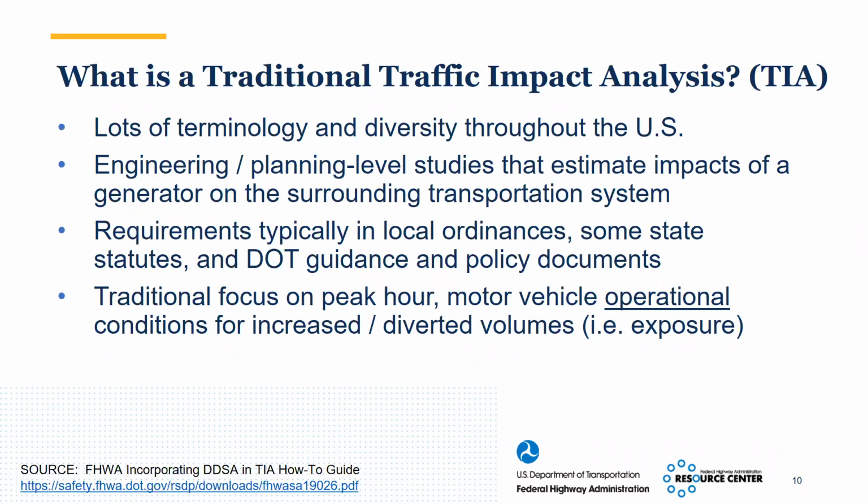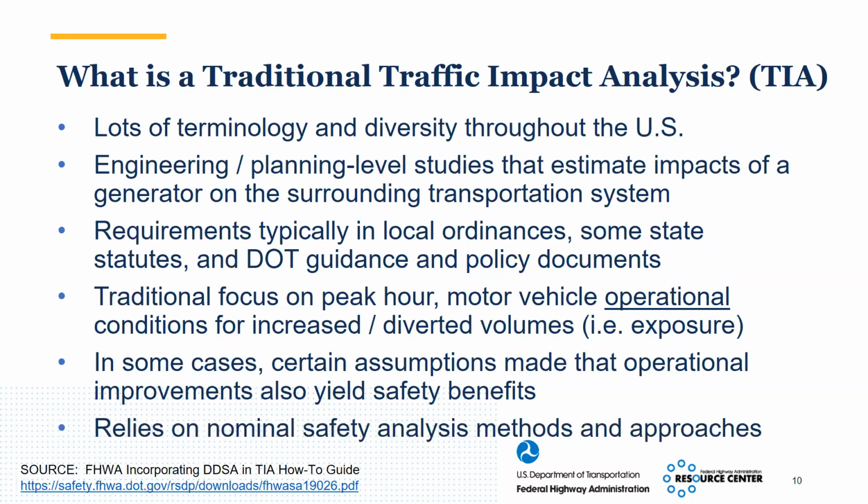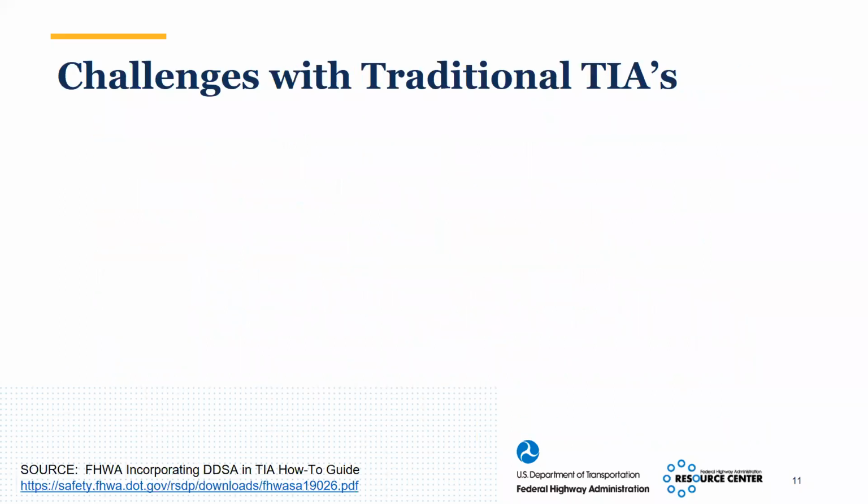But traditionally, they have a limited focus. Traffic impact studies focus in on motor vehicle operations and measure what happens if you increase volume, move volume, decrease volume, i.e. change exposure. And in some cases, there are assumptions that what we do to mitigate, quote unquote, operational impacts may also have some direct safety benefit. That's an assumption perhaps that might work in some cases and might not in others, but we do know in many cases throughout the nation that nominal safety approaches are what are used through traditional traffic impact studies.